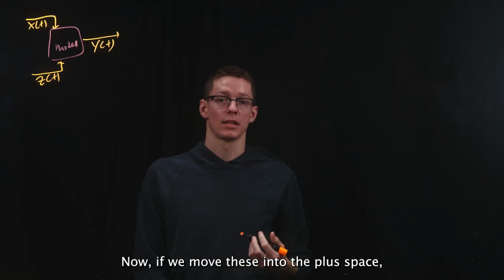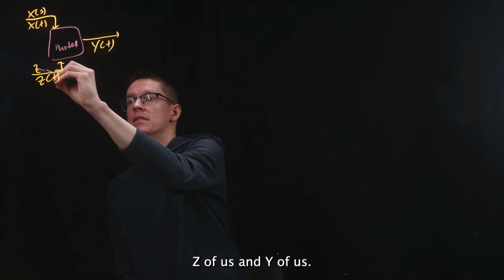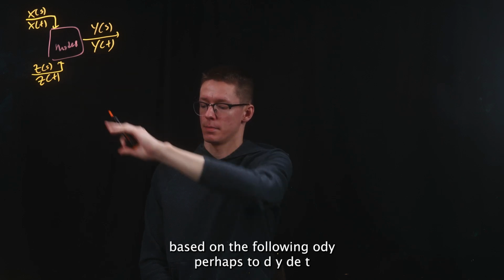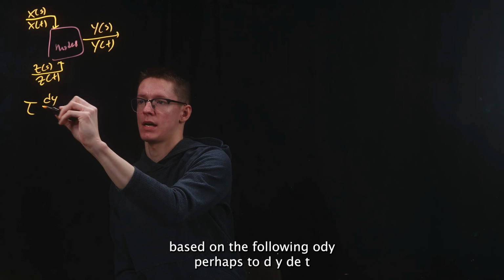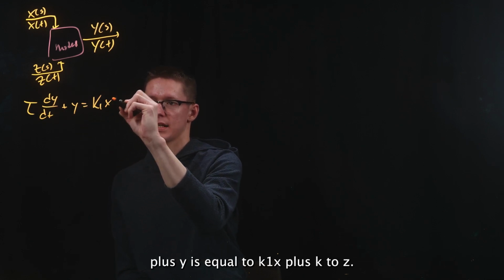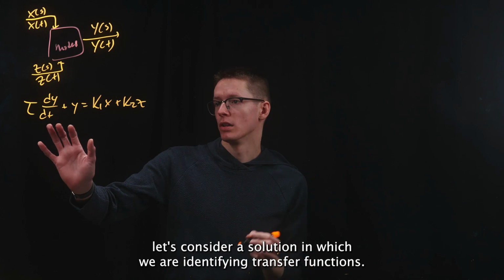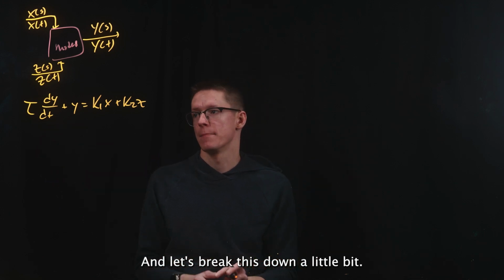Now, if we move these into the Laplace space, these will end up becoming big X of s, Z of s, and Y of s. So if we are able to then describe this model based on the following ODE, perhaps tau dy/dt plus y is equal to k1 x plus k2 z. And if we're able to use this ODE to describe this, let's consider a solution in which we're identifying transfer functions, and let's break this down a little bit.